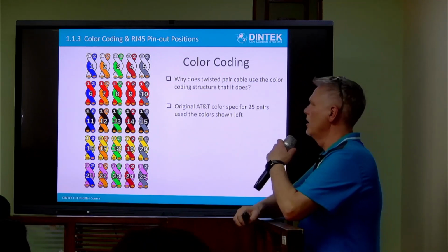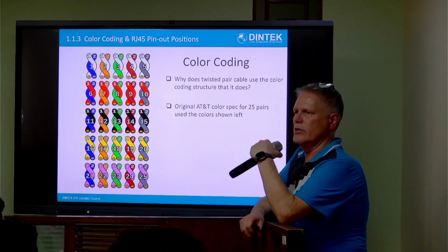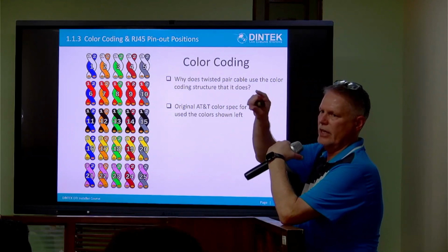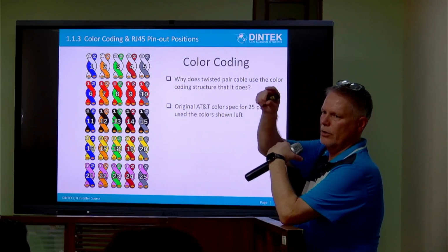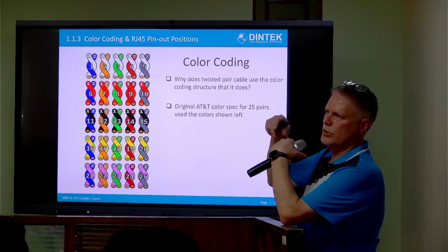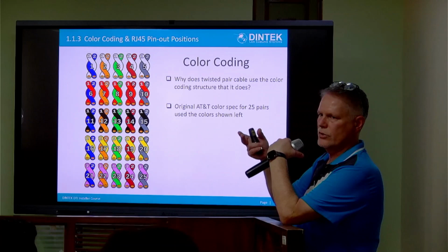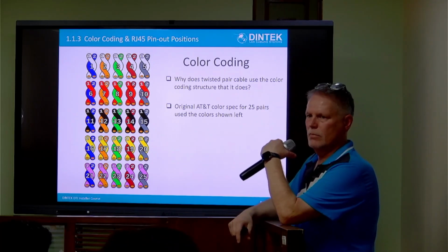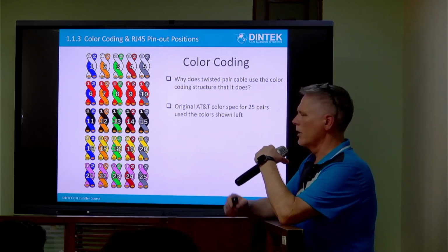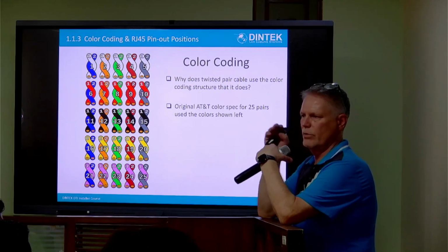For wire mapping, okay. Well, we'll talk a bit more about wire mapping when we do testing. But wire mapping is testers which actually cycle through each pair. So they're testing for connectivity between each pair on each positive and negative side of that pair. And it will show up things like if the pairs are reversed at one end, if they're open circuit, if they're closed circuit, if they're reversed with another pair, and it picks up through the wire map test. I'll show you when we do one of the workshops, we'll use some wire map testers, so you'll be able to use them and see how they work.